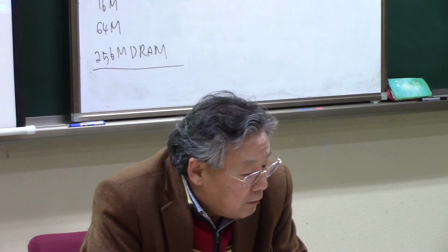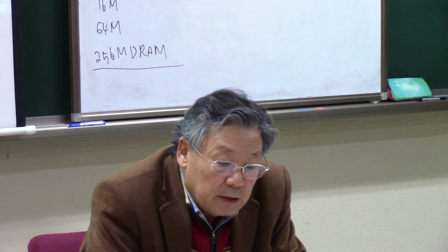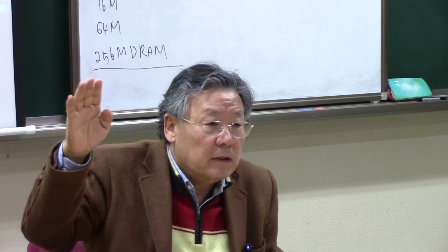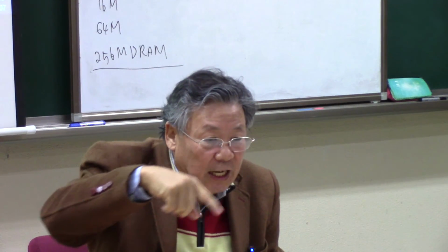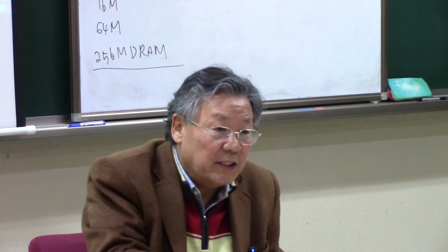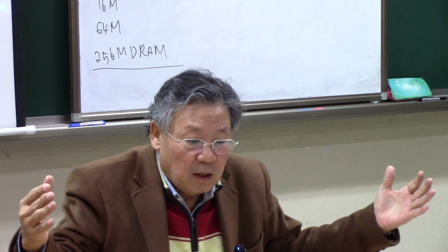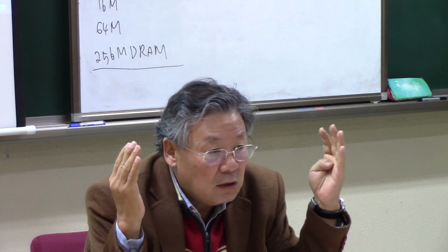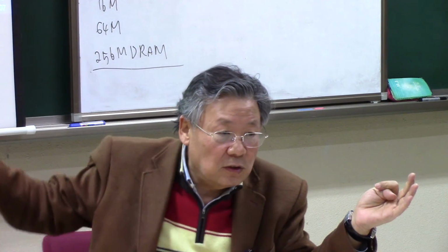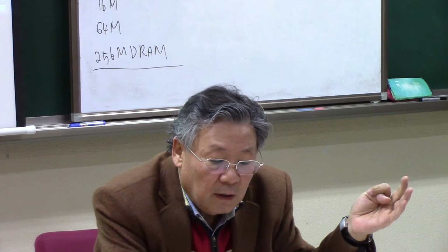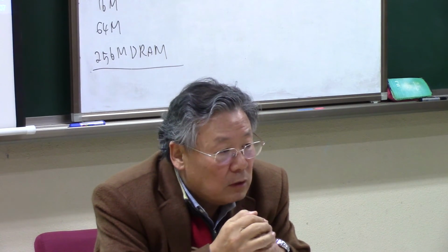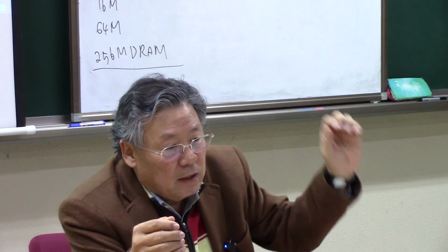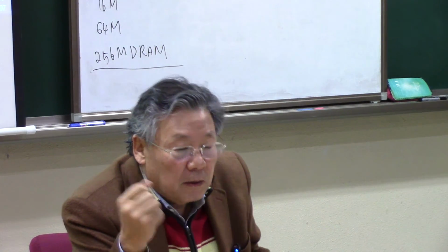So the factors related to the yield are the wafer size that we talked about. The dies on the edge of the wafer are going to be wasted, so we have to increase the wafer size. So wafer size is related to the yield, and die size, of course, as you have seen here, and the process number, how many processes have to be implemented to make a transistor.